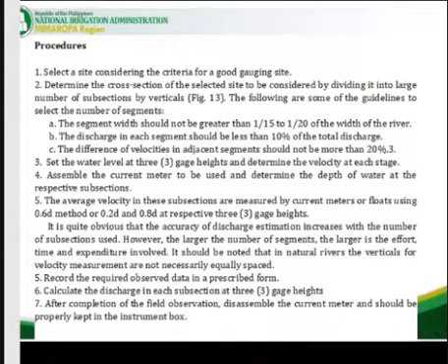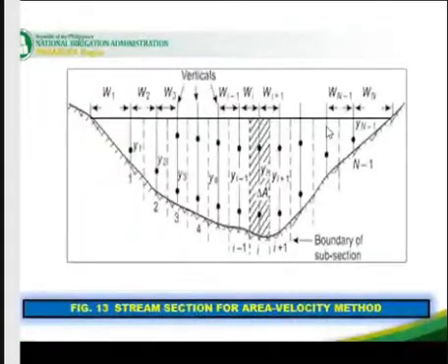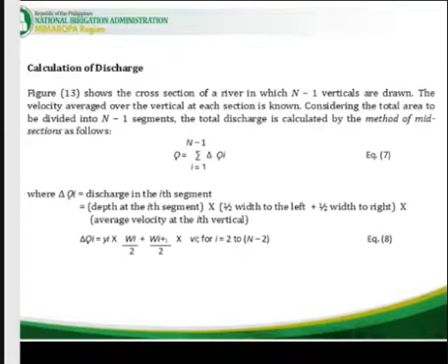But you can also use 1 over 15, depending upon the engineer concerned. The discharge in each segment should not be less than 10% of the total discharge. Okay? Please proceed.